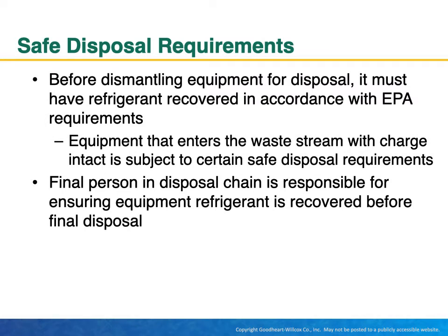Safe disposal requirements. Before dismantling equipment for disposal, it must have refrigerant recovered in accordance with EPA requirements. Equipment that enters the waste stream with charge intact is subject to certain safe disposal requirements. The final person in the disposal chain is responsible for ensuring equipment refrigerant is recovered before final disposal.